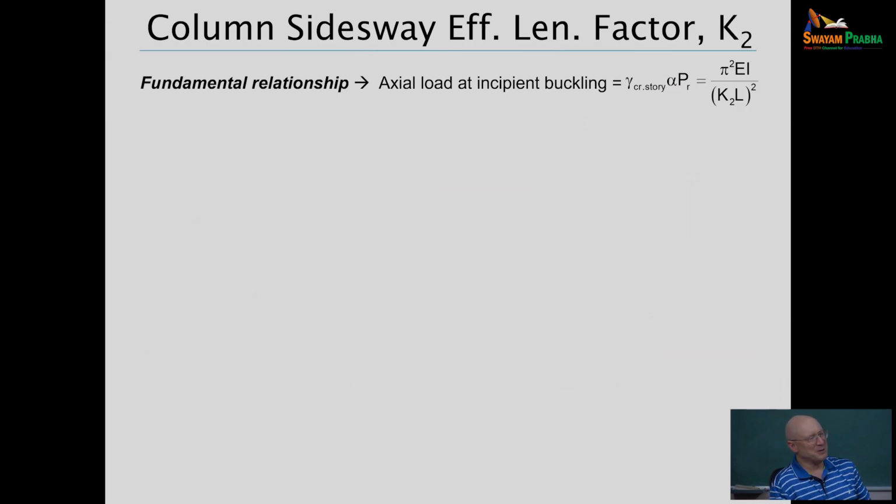All right, we talked about the effective length factor K1 for non-sway yesterday. And again, remember, I emphasized at the beginning of class today that you don't need the K factor. You just need the axial force in the member at incipient buckling when you design from that. So if you're using computations, you can work straight from that. But you still may want to calculate a K factor because it helps you understand what's going on, right? And that's where I always tell my students at Georgia Tech, the effective length method is a misnomer. It's the buckling analysis-based method. It's not the effective length method. With that said, let's talk about getting a side sway effective length factor.